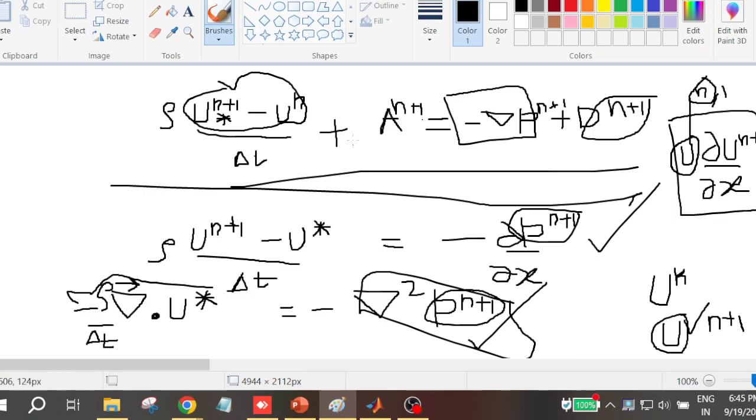Otherwise what would have happened is that in one go we usually calculate u star, and in one go we calculate v star. That would not be possible. What we have to really do is solve all u star, v star, and then the pressure Poisson, and then again come back and use the previous iteration u.